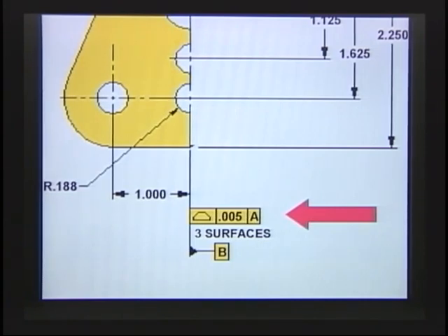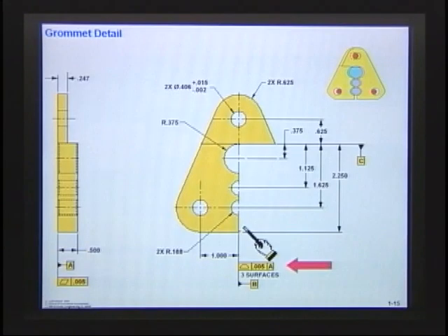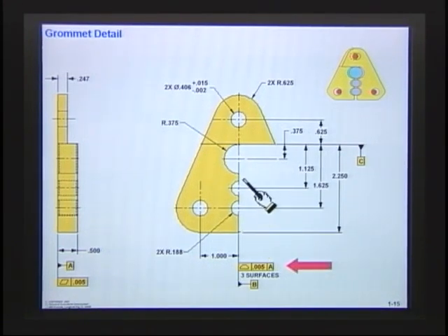And why a perpendicularity wouldn't work is because if I'm talking about these faces here, and there are 3 of these faces, you see, 1, 2, and 3. If I put a perpendicularity, you know how perpendicularity works. This surface would be perpendicular, this surface is perpendicular, and this surface is perpendicular, but perpendicularity doesn't make anything in line. It just says this is perpendicular, so this may be perpendicular out, this may be perpendicular in, this may be perpendicular out.